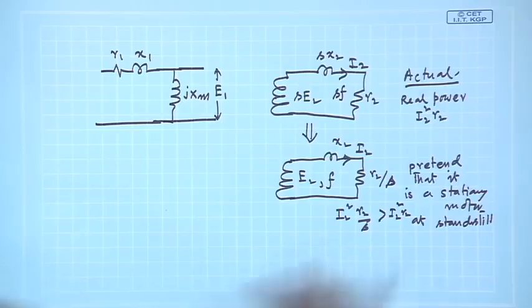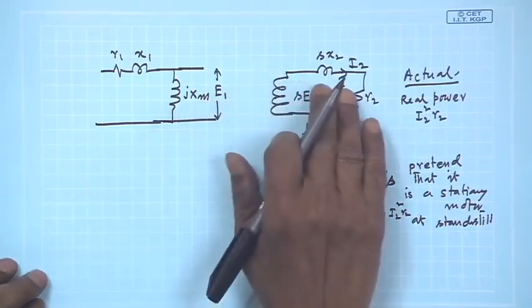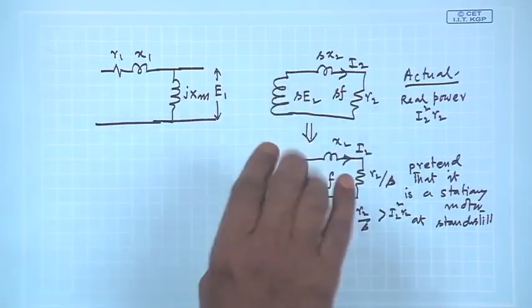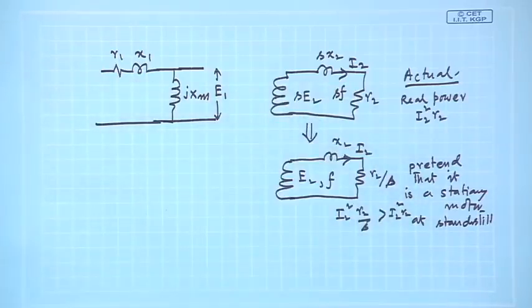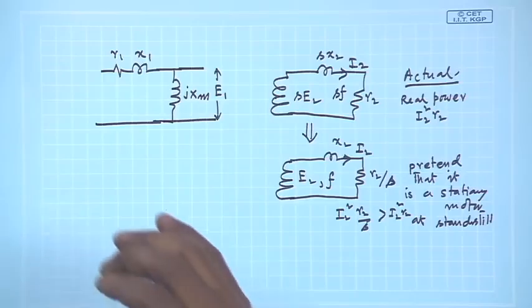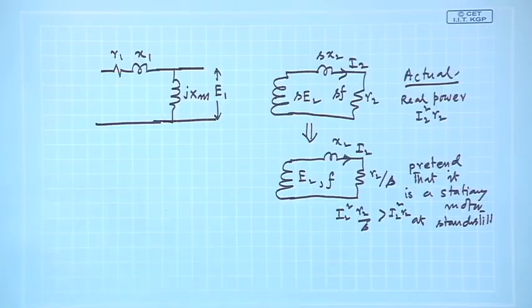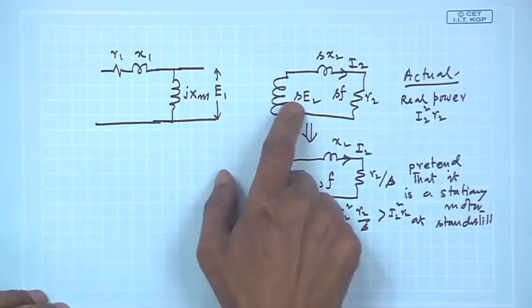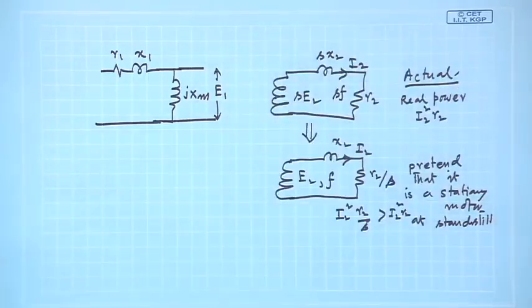Then how to explain that thing? I mean, what to do with that? Okay, now it is not at all surprising, because in this case the motor is running, and the motor will run with some slip which is not equal to 0 when there is an opposing torque. Mind you, this we explained last time. Had there been no opposing torque absolutely, slip would have been equal to 0, then this induced voltage is 0, no question of current, nothing.